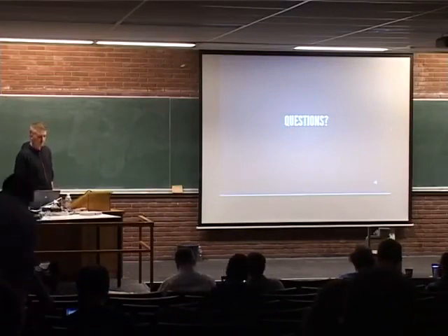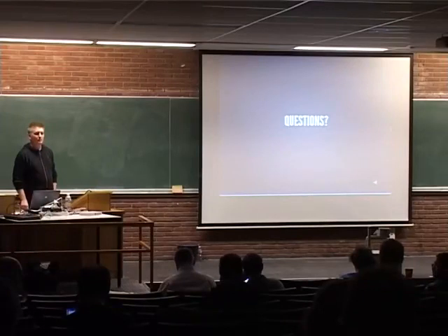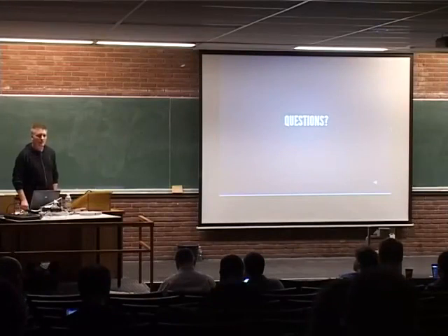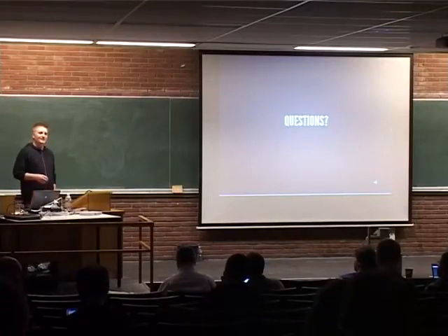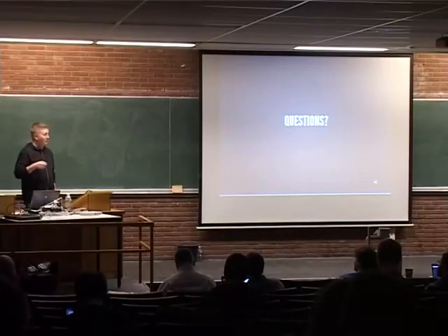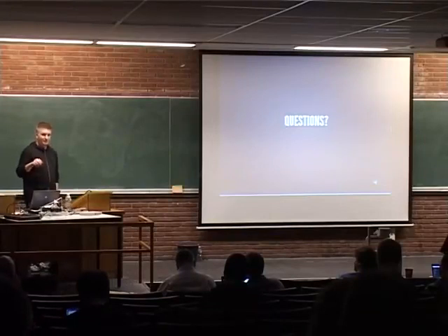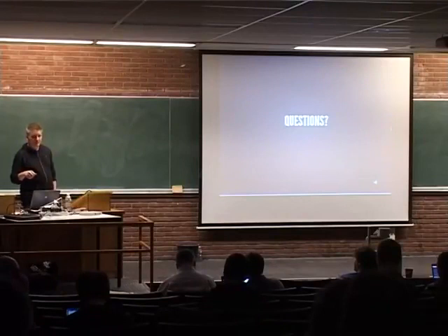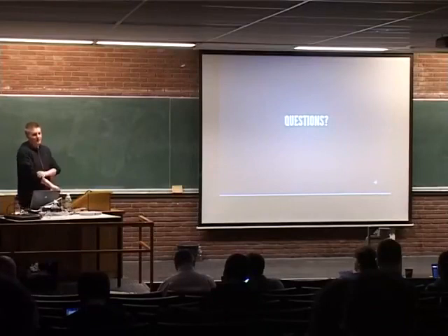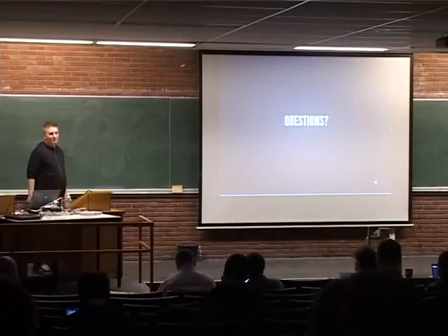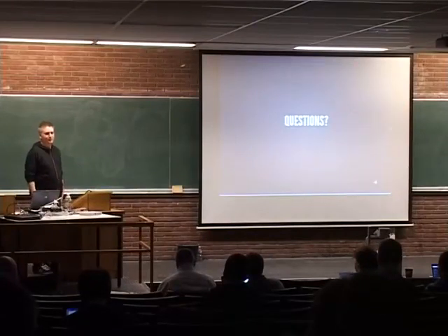How does the old NVIDIA stuff, which Nouveau drives, the desktop stuff, Tegra and Kepler, how do they all relate? If you don't mind me asking. It's independent technology. It's a different thing. No relation. Tegra, apart from the vertex shader being NV30 basically. The vertex shader is based on the OpenGL ISA. Even the bit fields are exactly the same. I'm pretty sure they're just bolted on that kind of vertex shader strip.